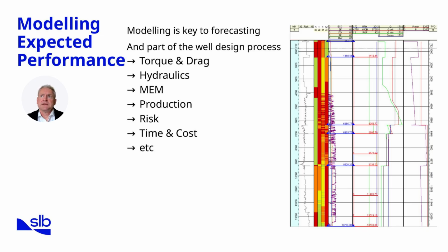Modelling expected performance is a critical part of the forecasting process and an integral part of well design. A forecast is only as strong as the models behind it, and these models allow us to test scenarios before the bit even turns to the right. Key modelling areas include torque and drag, which help us understand the mechanical loads acting on the drill string. Hydraulics modelling ensures that mud circulation is effective for hole cleaning and pressure control. Mechanical earth models predict rock strength and stress, guiding casing design and wellbore stability.